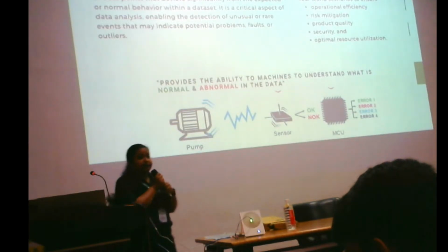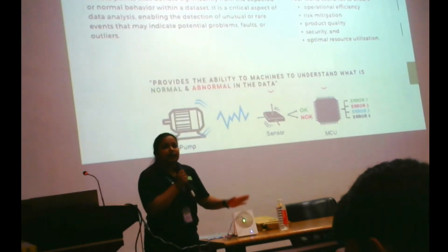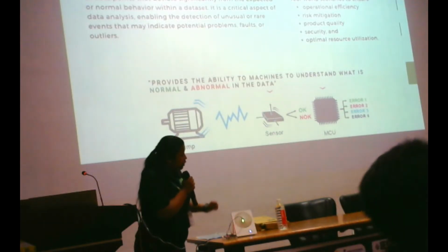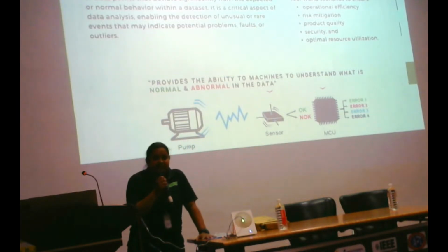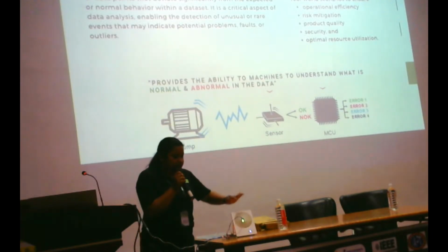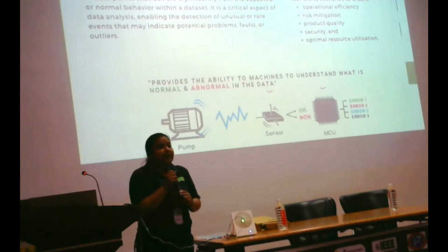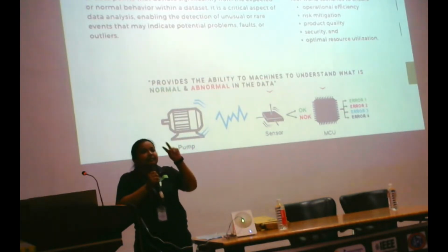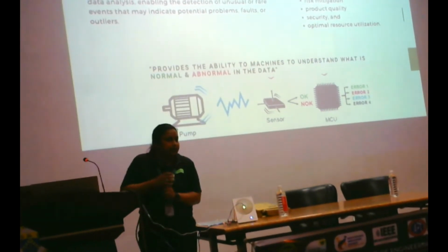So, the objective will be to detect the anomaly of this fan, whether it's giving a good vibration, like a good signal, or a bad signal. Here I have connected the sensor. This sensor is basically a motion or motion vibration sensor. It is a 6-axis motion sensor, because 3 axes are for the accelerometer and 3 for the gyroscope. So it has two parts; it gives gyroscope values and accelerometer values also.